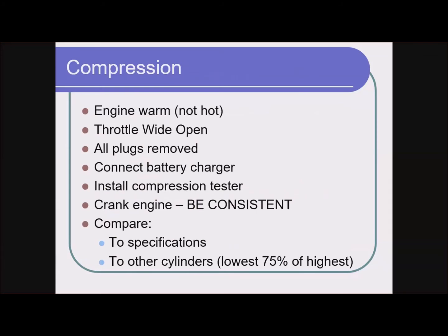So how do we do the compression test? Well, obviously we need a compression tester. We want the engine ideally to be warm, but not hot. Why? So why do we want it warm instead of cold? Well, when engines are manufactured, all of the tolerances, clearances, things like that are all specified for an engine at operating temperature.